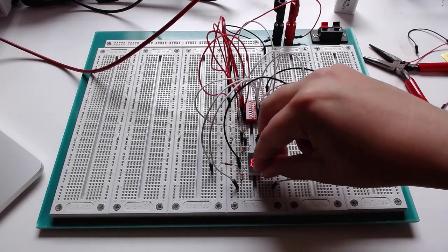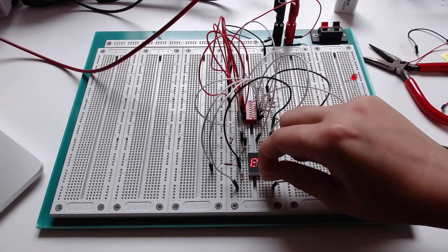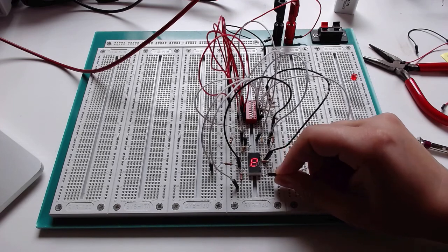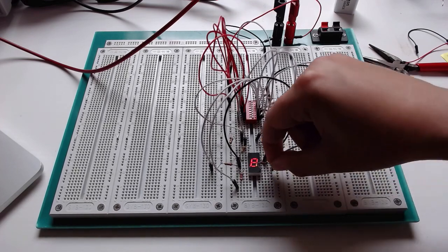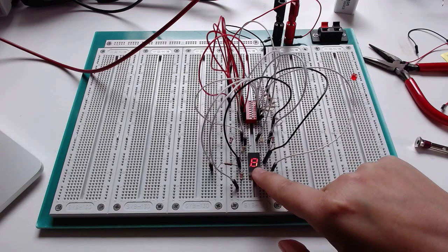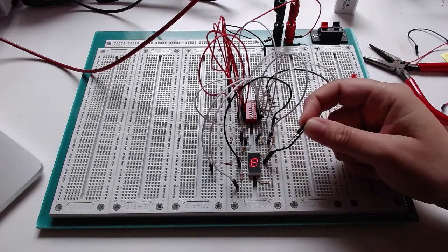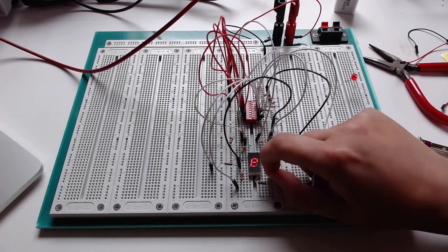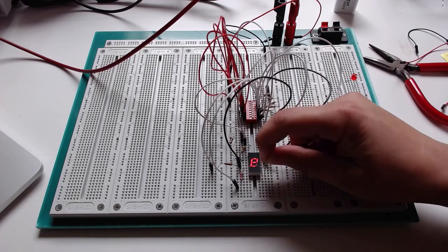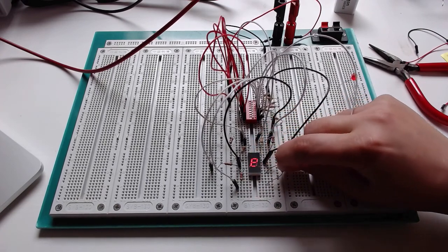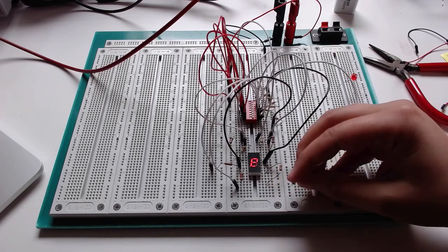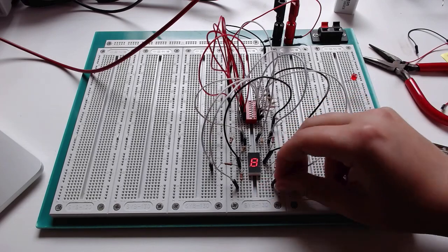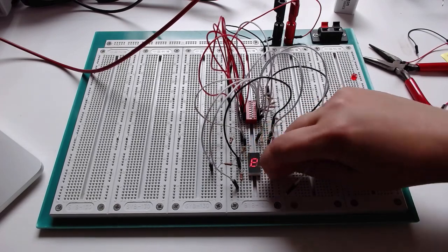Another very common thing that I see, and essentially it's the same thing as before, is that students will take the resistor, short both legs in the same row, and stick the signal wire in. Well, look, it's glowing orange and it's warming up. That is essentially like having no resistor here. We've discussed this issue before. When both legs of the resistor are in the same row, then it's like the resistor is not connected at all. So we need to take one end of that resistor and put it into a completely different row and then connect it.